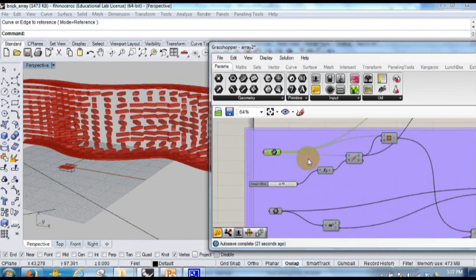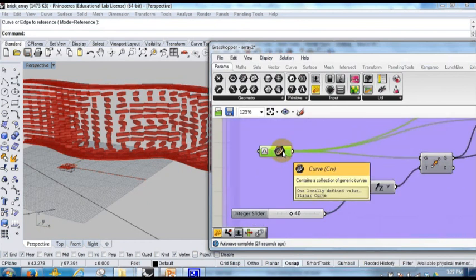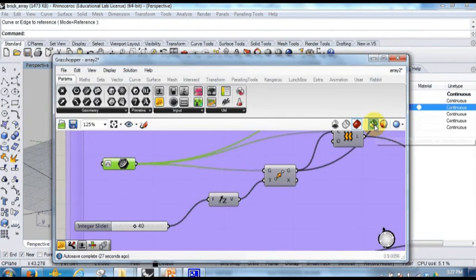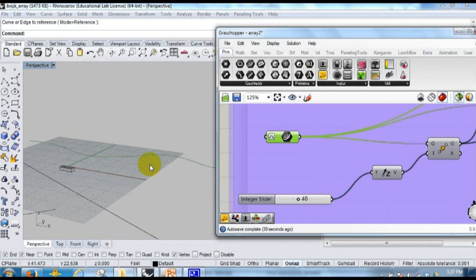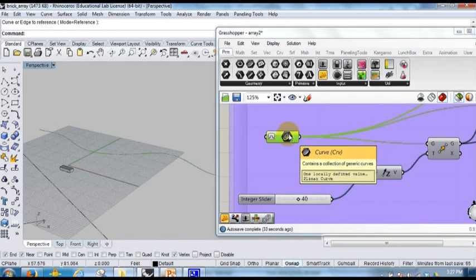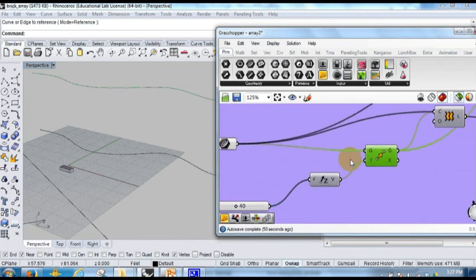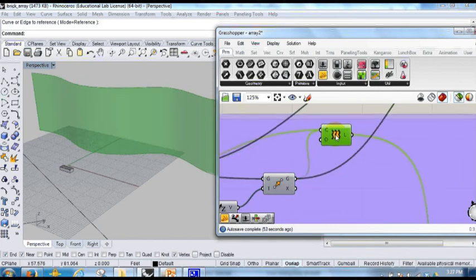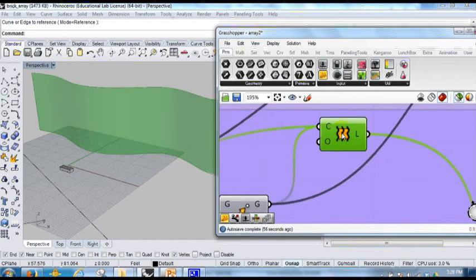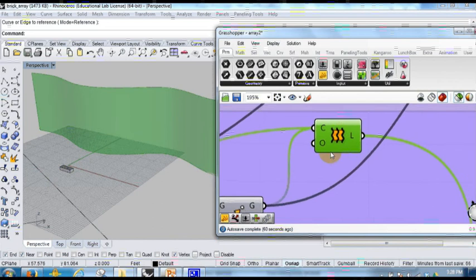I will start with the curve. All right, the first thing I do, let me just turn on the green box. So first I load the curve in, right? Simple. And then I move the curve along the z-axis. Just move it up. So here's the z, and here's the distance I want to move. So you can see the curve has been moved up, right? So I have two curves right now. And then I did a loft. I think I covered this last class, right? Loft is basically creating a surface based on two curves. So you get a surface.